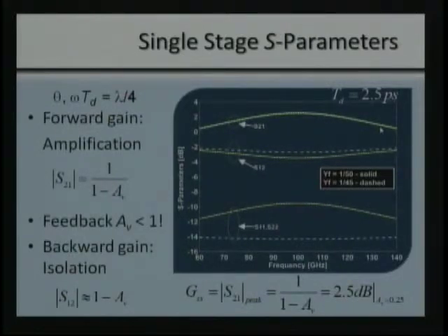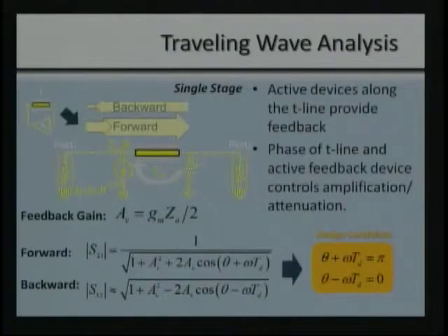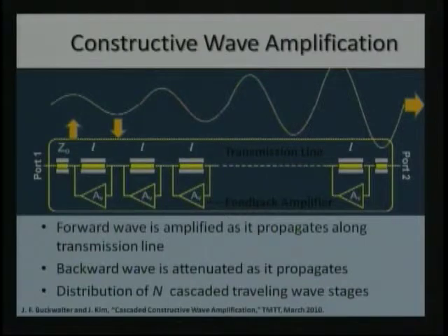So you can think of the S parameters for the transmission line as degenerating when AV is 0. We simply have a transmission line between port 1 and port 2, which means that any wave will just travel down that transmission line and reach the second port unencumbered. It's the same amplitude, just delayed.